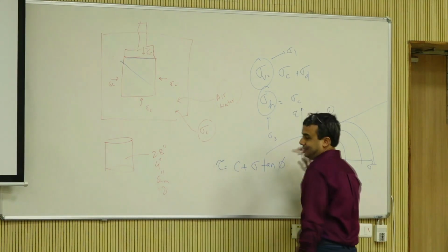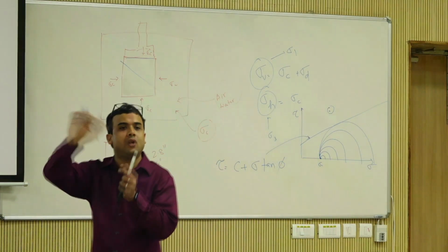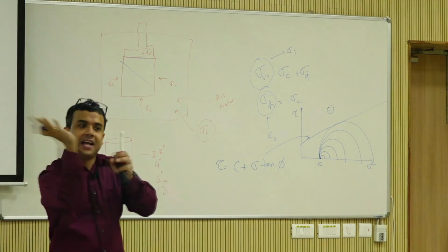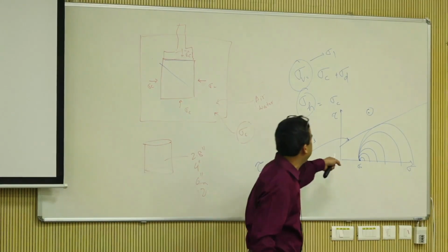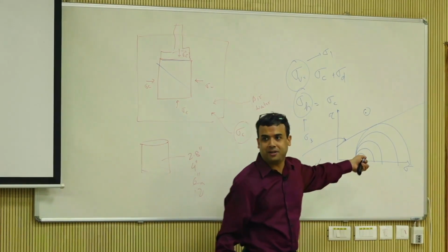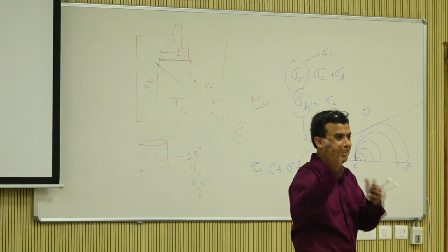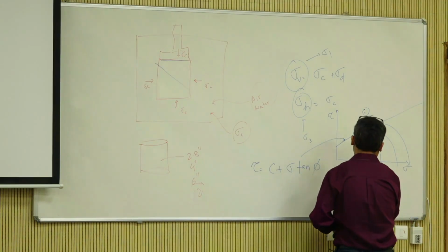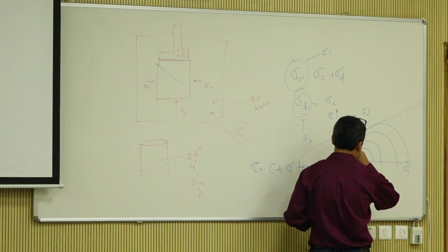So a little bit of additional information for you. The Mohr Coulomb envelope is actually non-linear in nature, but you are doing a linear interpretation, and that is the reason you a lot of times have the C or an interpretation C. So you just have to remember that it's not truly linear, it's a non-linear envelope. Okay. Now this is sigma 3, this is sigma 1, that's the major principal stress, minor stress and stuff.